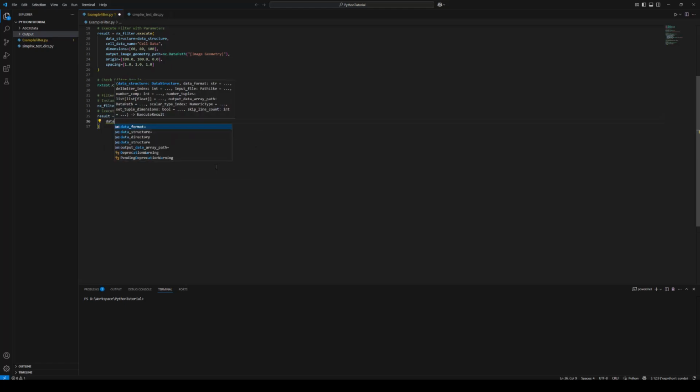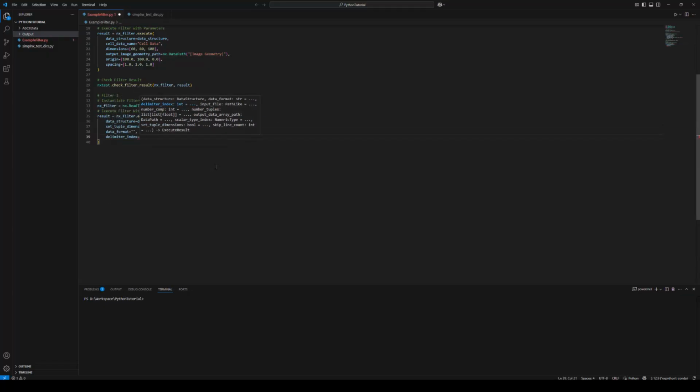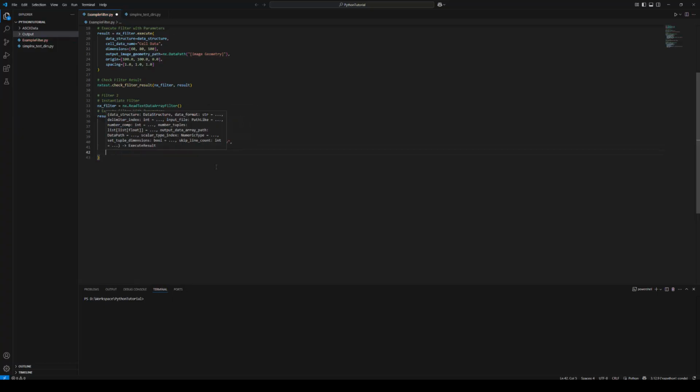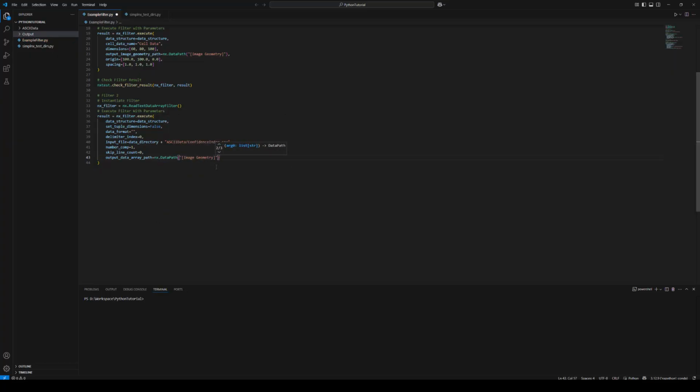This step specifies how the CSV file is imported by defining the input file path, delimiter, skipped header lines, tuple dimensions, numeric format, output data path, and floating point precision. These settings ensure the raw text data is correctly parsed, typed, and placed into the correct location within the geometry's cell data.